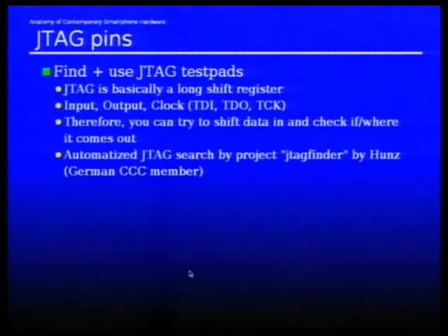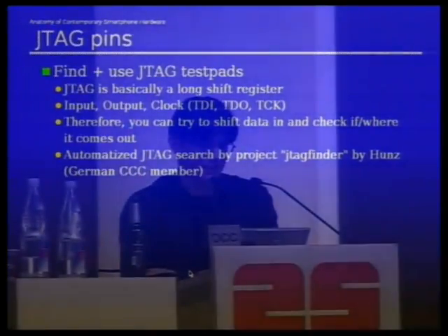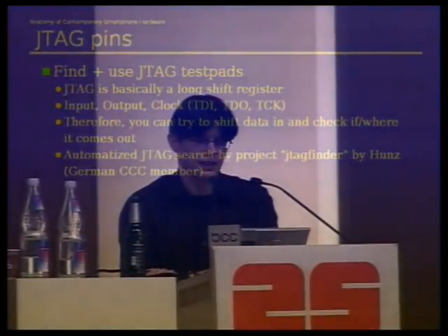And luckily, there is now a sort of a more efficient method, because JTAG is a long shift register, and you have input, out, and clock, and you can try to shift data in somewhere and see whether the same pattern shifts out somewhere else a defined number of clock cycles later. So there is a JTAG Finder project in hardware called JTAG Finder, which Hunz from the CCC, I'm sure he must be hanging out somewhere here, has implemented. And basically, you connect all the pads at once.